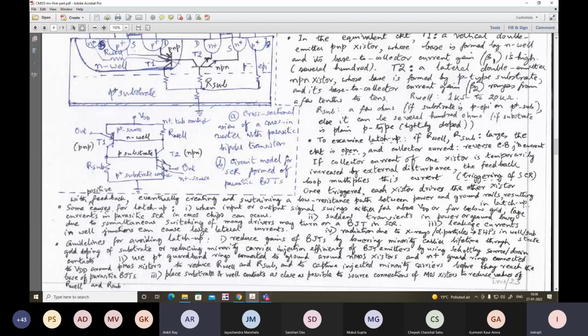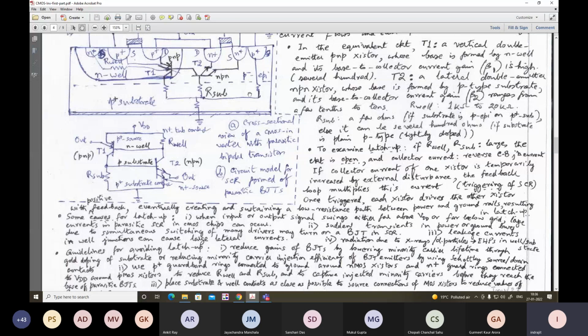In general, the vertical bipolar junction transistor demonstrates higher beta values than the lateral one. But why exactly? One reason I can tell, but you please verify. All of you please verify. What is the basic operation of the bipolar junction transistor? As far as the doping concentration is concerned, the emitter should be the most heavily doped. The emitter has the highest range of doping density of carriers, say for an NPN transistor.